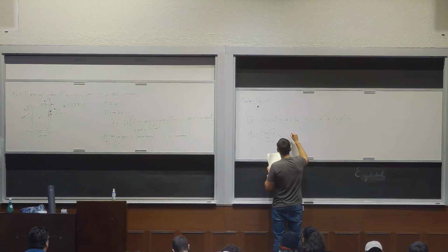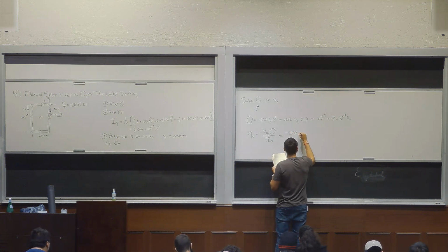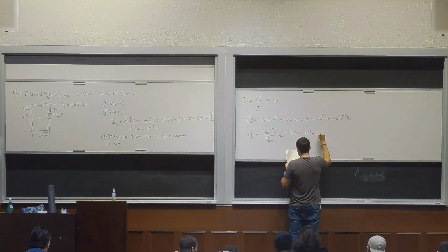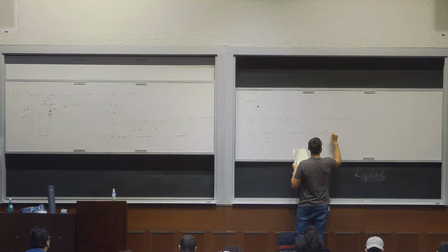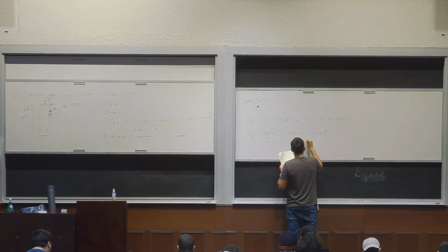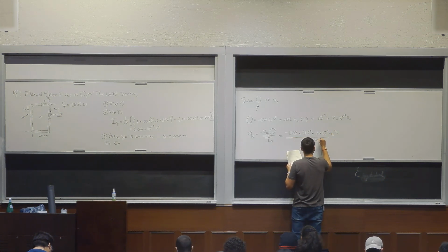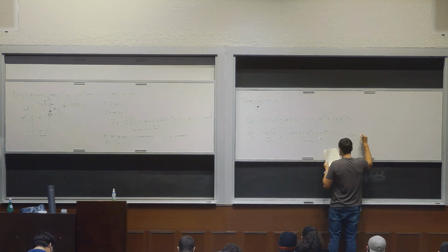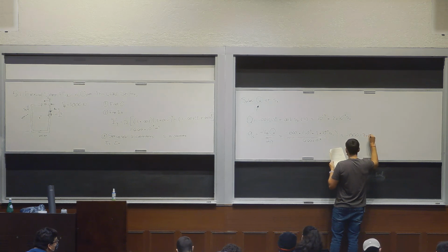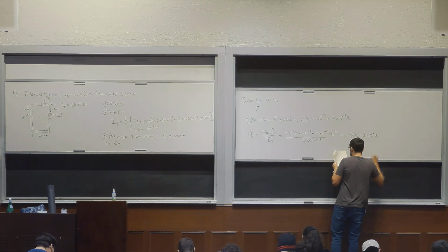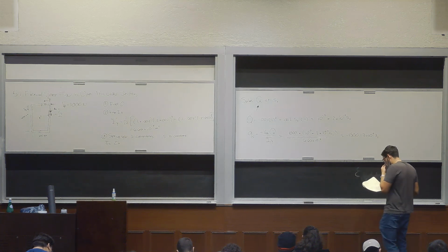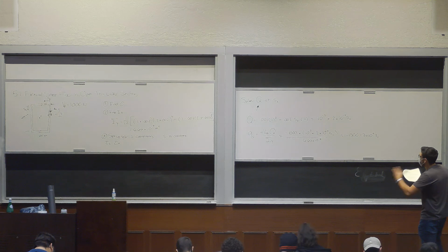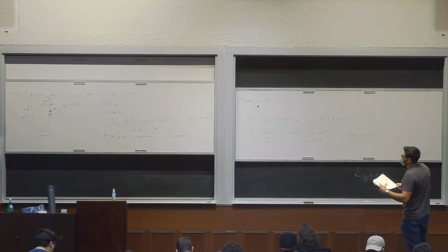So negative 1,000 times 10 to the negative 5 plus 2 times 10 to the negative 4 S2, over 6.66 times 10 to the negative 6. That equals negative 1,500 minus 3 times 10 to the 4th S2. So that's how the shear flow varies with S2.